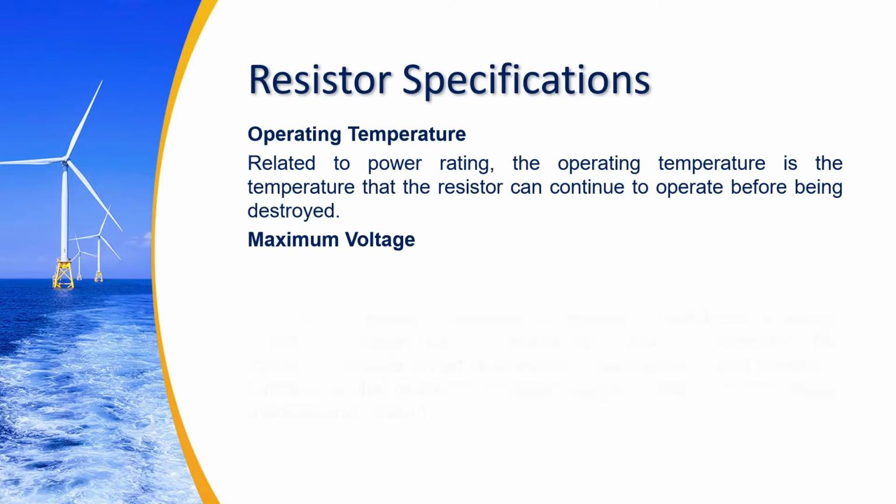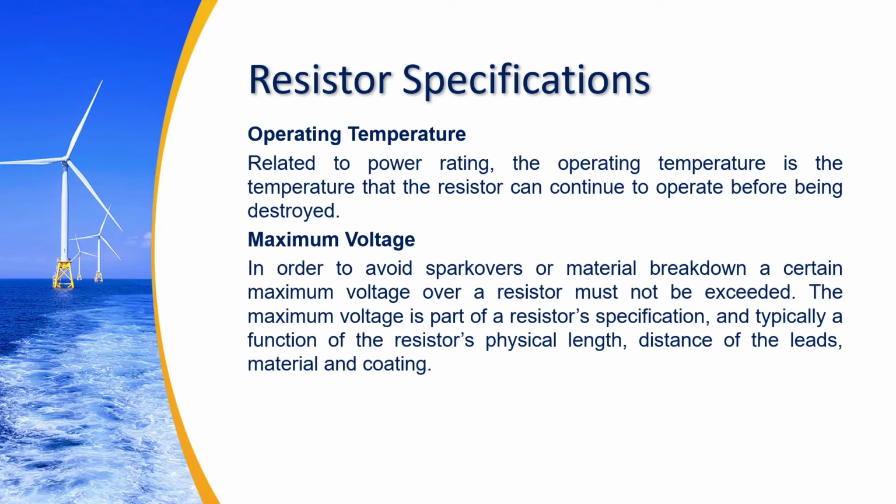So, maximum voltage. So, in order to avoid spark overs or material breakdown, a certain maximum voltage over a resistor must not be exceeded. So, the maximum voltage is part of a resistor's specification and typically a function of the resistor's physical length, distance of the leads, material, and coating. Okay? So, ito naman yung maximum na boltahe lang na kayang i-support ng resistor natin. So, kapag na-reach na yung maximum voltage or nag-exceed siya diyan sa maximum voltage, possible din na mag-breakdown yung resistor natin.